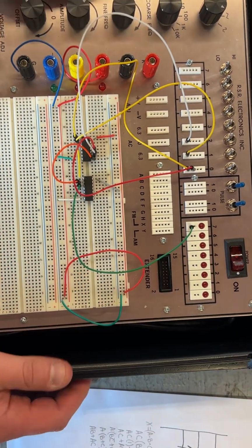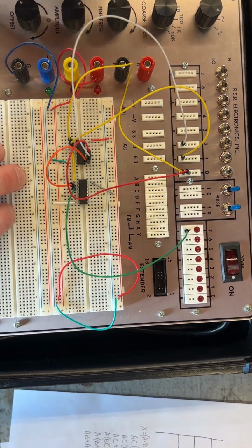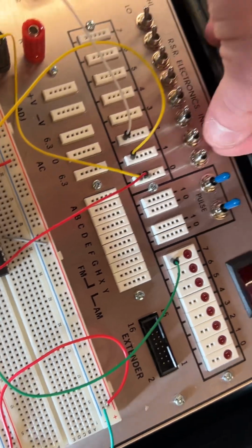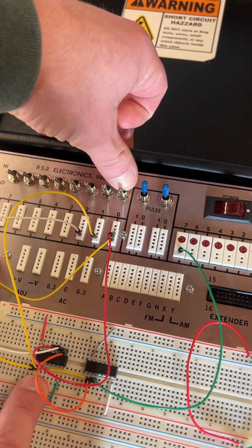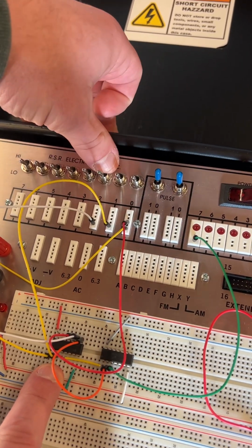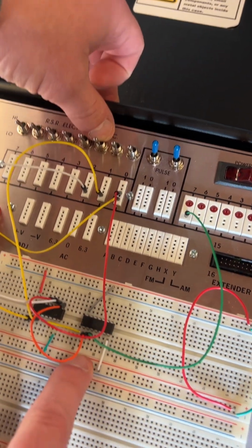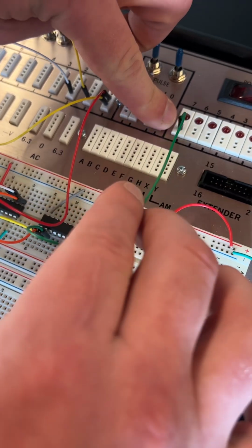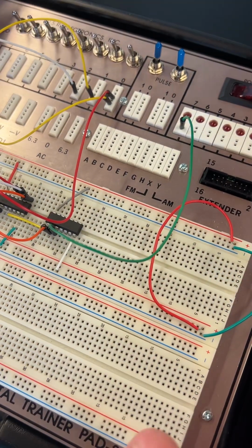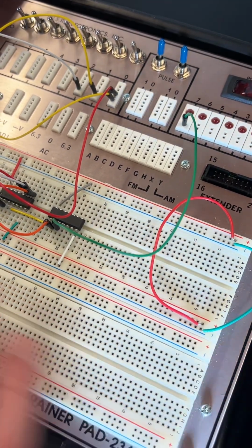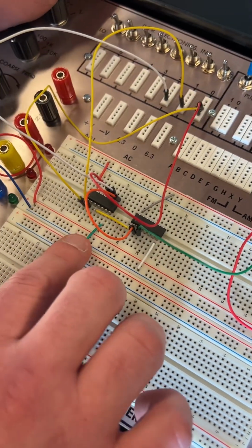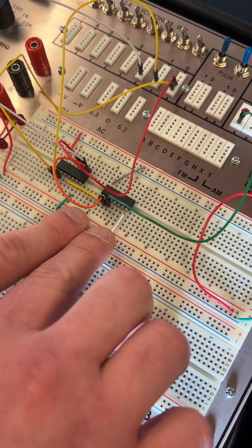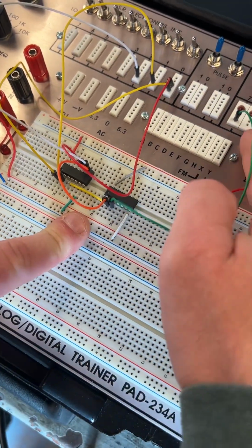Basically what you're looking at here is we have our pin 1 and pin 2. Those are going to be wired up into the switches up here. So our 0 is our A, our 1 is our B, and our 2 is our C. Since we do have an OR gate here, to make this LED light, which is what the output of the OR gate goes to, we have to take all of our outputs from this AND gate, and instead of running those to the LED, we run those into the input of this OR. And then the output is what's going into that LED.